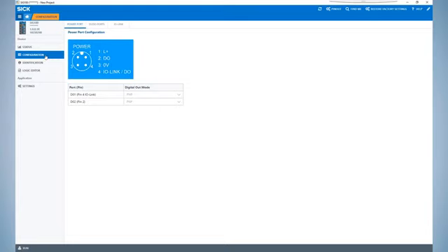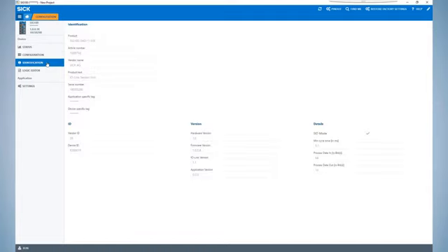This includes the 6 main M12 ports and the power port. It also allows the user to toggle between digital and analog in the process data out for the IO-Link data frame. The identification page simply provides product details for the connected SIG 100 like software and firmware revision number.